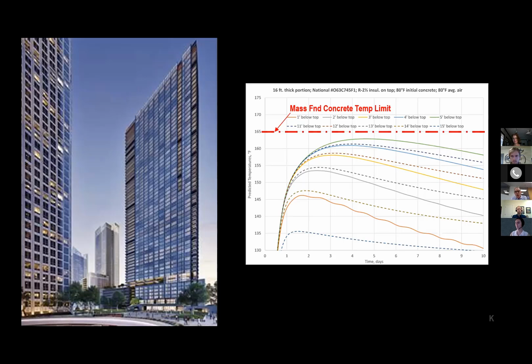But what really was one of the biggest interventions was looking at that aggregate supply and storing those Polaris aggregates, not at the batch plant, but storing them down by the water where we had better natural cooling and a natural lower temperature, and then simply protecting the rock, putting the cover over it.